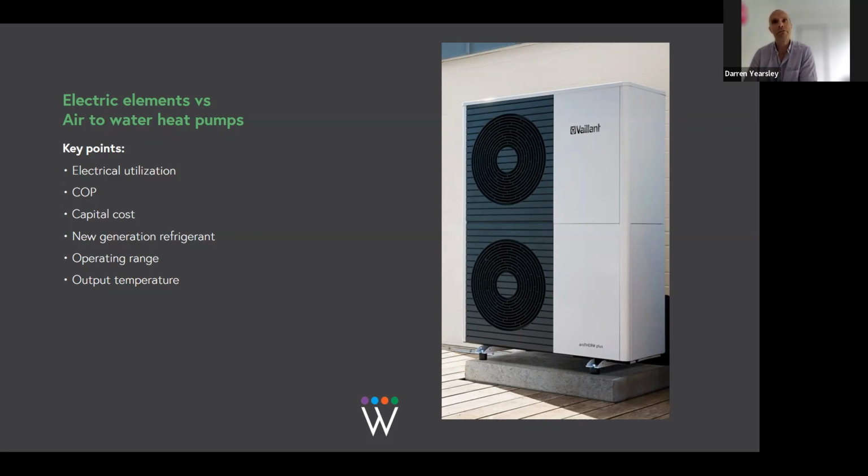So if I give a high temperature air-to-water heat pump 1 kilowatt worth of electricity, it can harvest heat from the air at a rate of 3 to 1. So 1 kilowatt in, 3 kilowatts out. So immediately you can see, okay, if you were going to state that in terms of efficiency, the heat pump itself is 300% efficient, which obviously doesn't make sense to me. How can you get more energy out than you put in? And it's because we're not directly converting the electricity to heat. We're using it to run this process. The heat actually comes from the outside air.